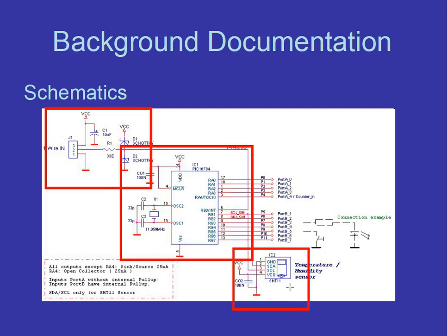And as you do the troubleshooting, you can study each part of the circuit separately and see what input you are giving to the circuit and what output you are getting, and whether your output is what you're expecting. If it is deviating from what you expected, then how much it is deviating, or is it totally off the reading?